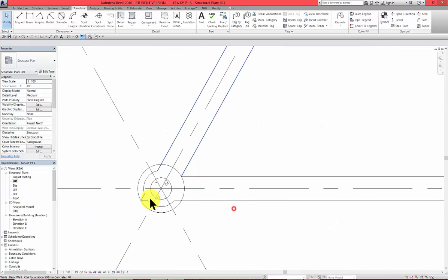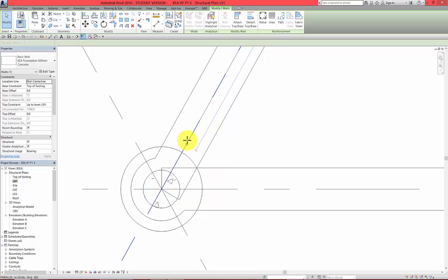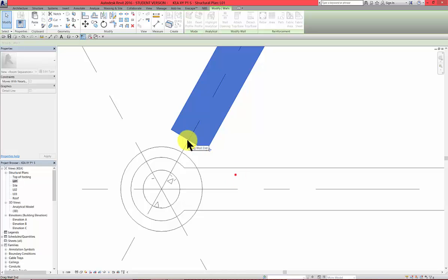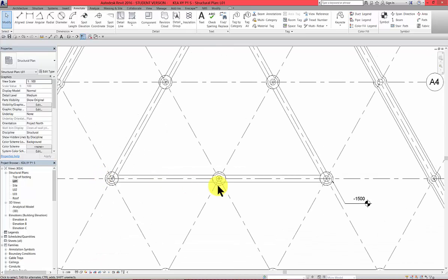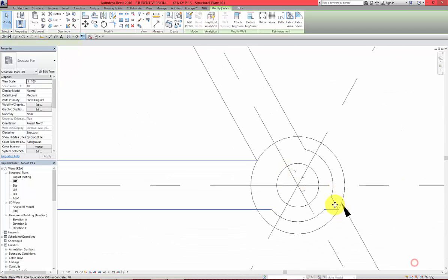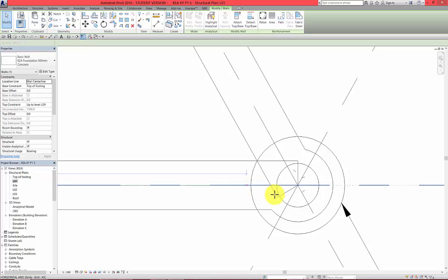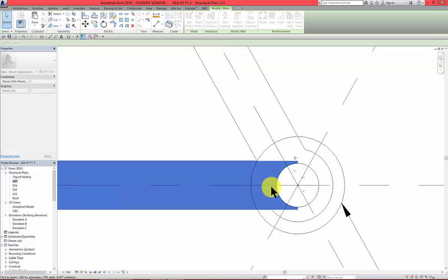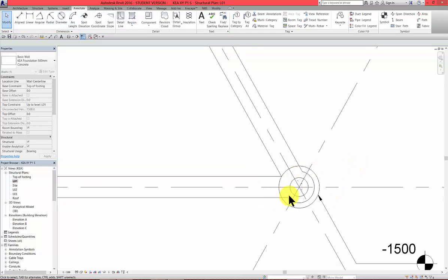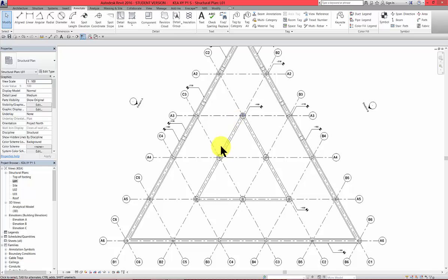Okay, the same with this one, select it, zoom in, blue dot, right click, disallow join, take it out and then bring it in, escape, and the last one here, left click, right click, disallow join, then zoom out, zoom in, not zoom in but bring up and down. Then this is fixed. Now the next thing is we need to create a step here.